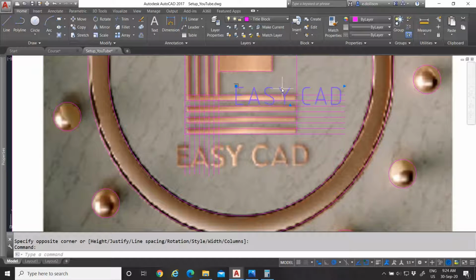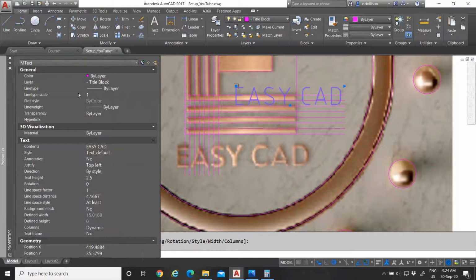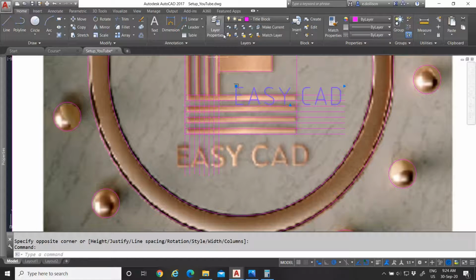As you can see here, my text is just lines because it is ISO, but I do not want it to be ISO. Where is the text name? Oh, it is set to the default text style, which is good. Let's just leave it as default.